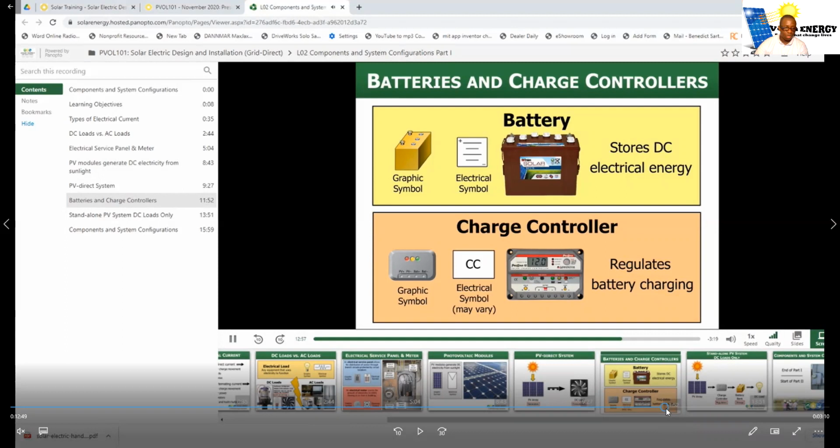That is one of the reasons why we're having a great problem in Liberia. I see a lot of people complaining that the battery in Liberia doesn't last. You need a charge controller to regulate the discharge. In that way, the battery will still have at least 20%. In America, it's recommended 50%. It depends on the battery. There's some batteries you can take as far as 80% discharge. We'll talk about that later in further training.